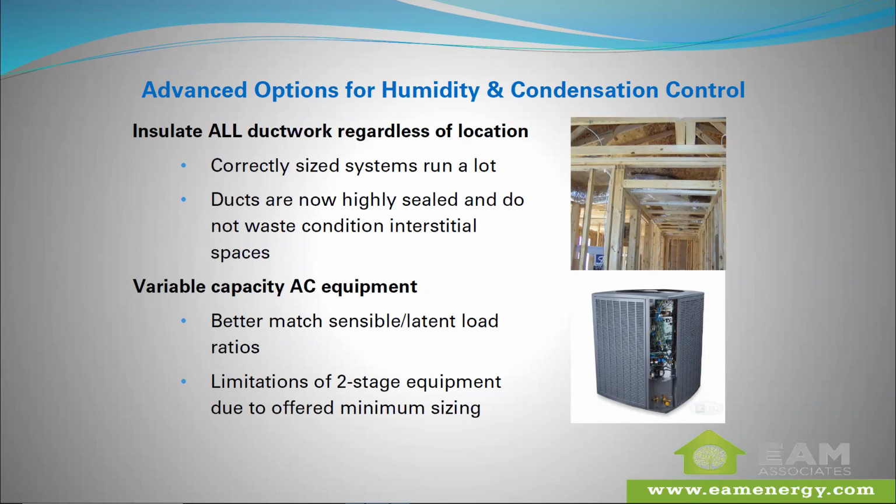It's certainly not the same as it being outside, but it's not conditioned space either. It doesn't behave that way. Correctly sized systems run a lot, and that's good. They're supposed to. They're machines, and when they're designed correctly, that's fine. But they do run a lot, and so your duct surface temperatures in certain locations are going to run down low. The ducts are also now, in most places with good energy codes, highly sealed, and they are not wasting conditioning on that interstitial space anymore. So just insulate the ductwork everywhere. You'll be glad you did. I know there's a little bit of a cost premium, but it's well worth it.